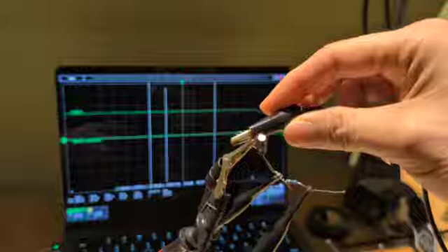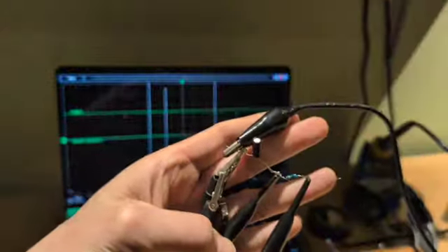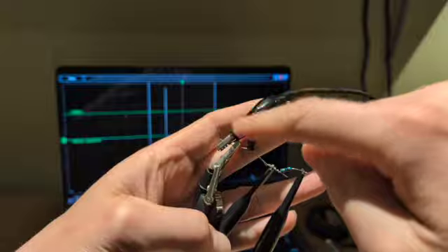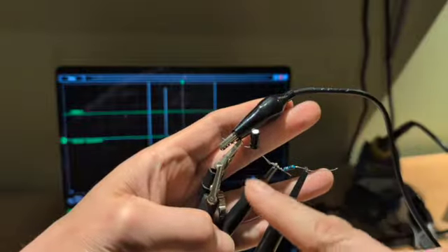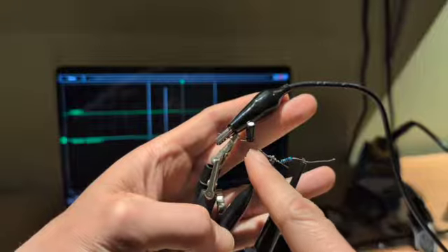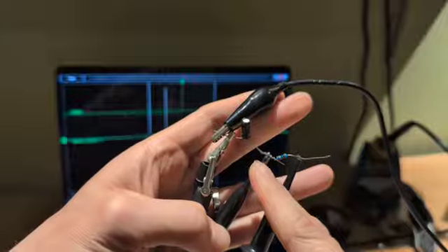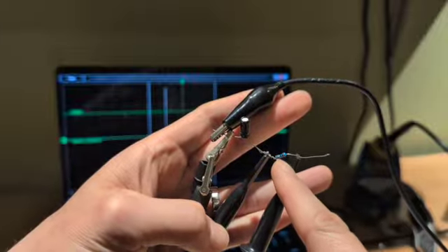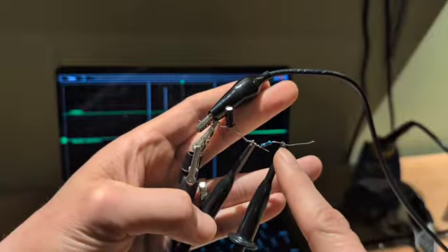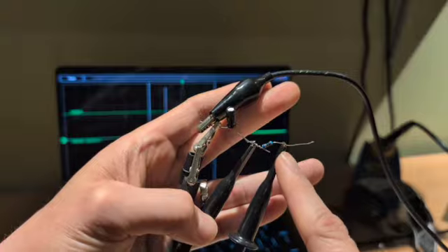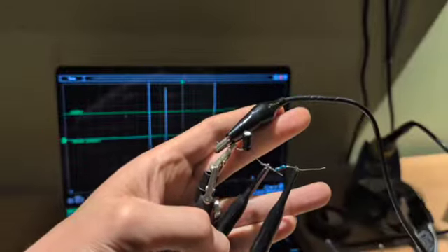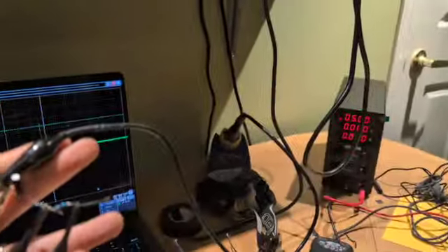I have now a power supply, and the negative end is connected to the negative end of the capacitor, and I have the probe connected to basically the positive of the capacitor. The resistor is a 100k resistor, 100k ohms, and I have another probe attached to this power supply. Now the power supply isn't connected yet, and I've set it up to be 5 volts here.